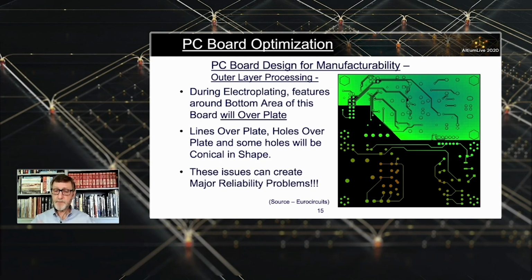A lot of people think pouring copper on the surface of a board is an automatic cure for EMI. Not true. It may help, but it may not. You have to attach it to the right voltage or ground depending on the other layer. So the point is, know what you're doing, pour copper all over the board and attach it to something.